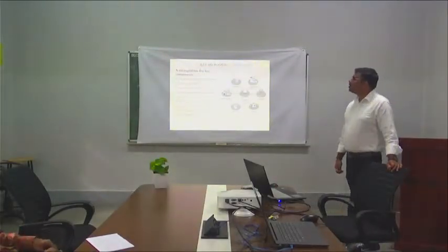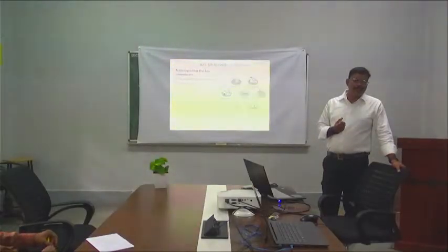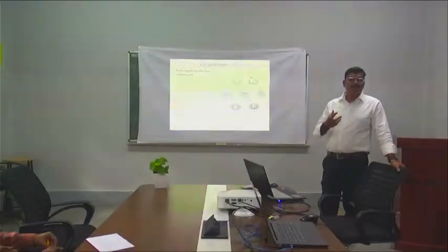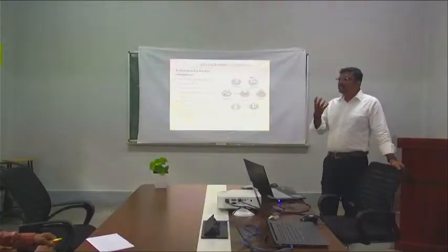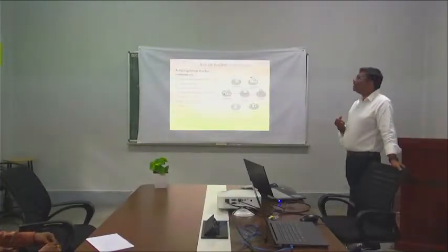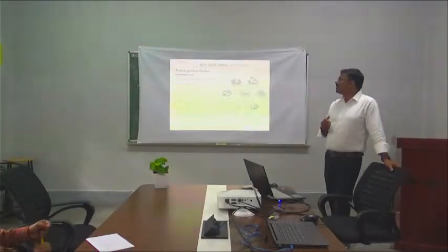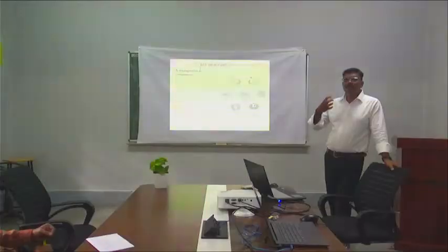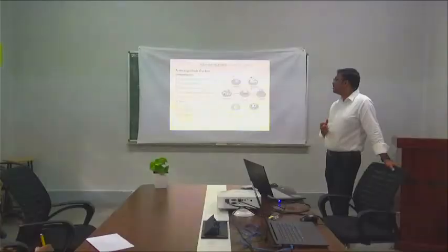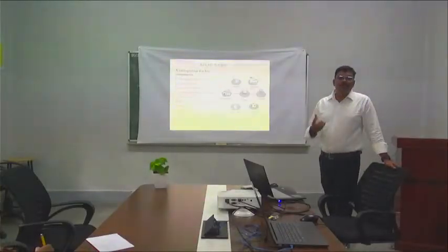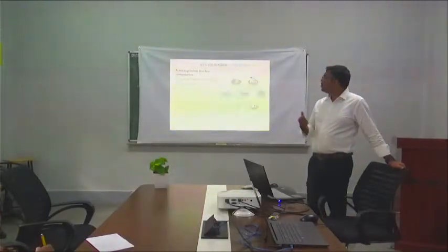What are the key components of a microgrid? When we talk about a microgrid, it consists of 5 key components. The first one is energy sources, that means generators are required, or an energy storage system, batteries, is required. The next one is energy sinks, that means loads must be there in the microgrid. And a connecting and disconnecting system, the means of connecting and disconnecting from the large power system. Sometimes when we have excess power, we can operate connected to the grid, or we can operate in isolated, autonomous mode of operation also. Controlling and regulating also comes into the picture. And safety measures, protection, is also one of the components when we talk about a microgrid.